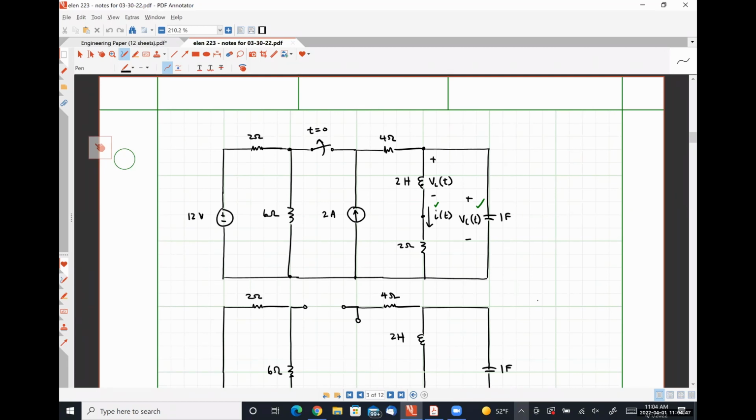We did a large amount of work to figure out what this quantity VC as a function of time is. Okay. So the first thing that we had to do was to determine what type of circuit this was. And we concluded that this is behaving like a series RLC circuit, because during the transient condition, with this voltage source turned off, we see energy transfer from our capacitor flowing through our inductor, and effectively it's just these three elements right here forming a loop, telling us how our transient condition is behaving.